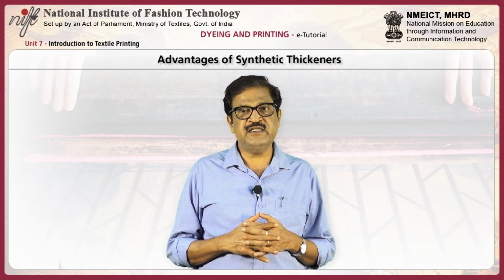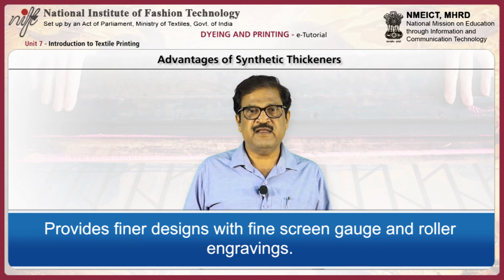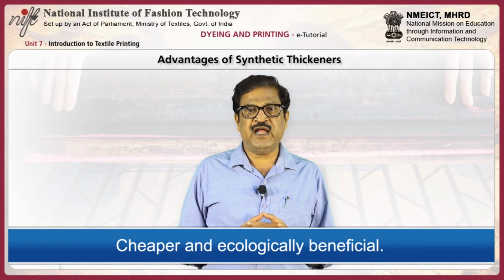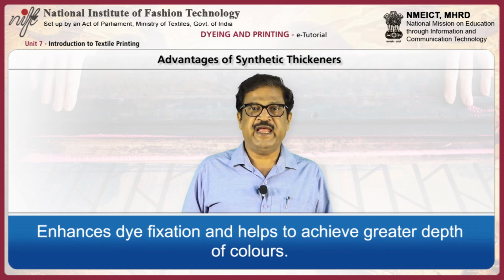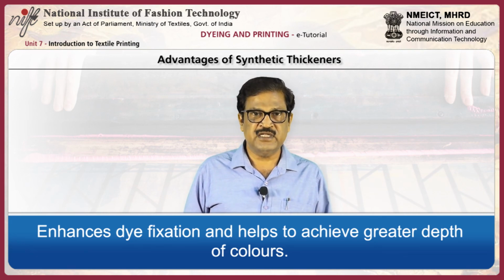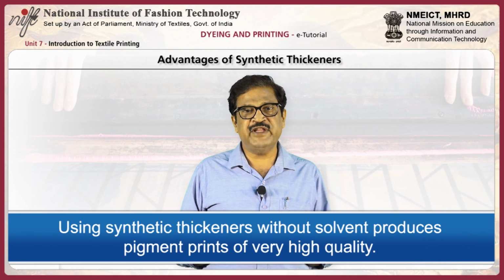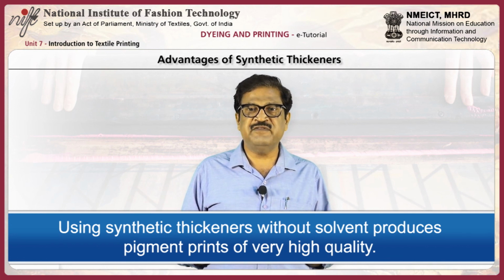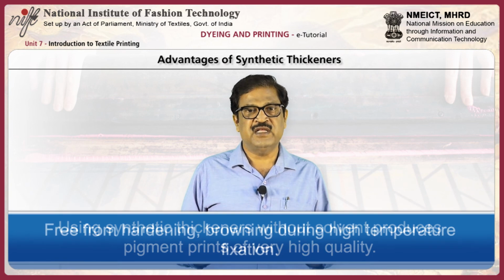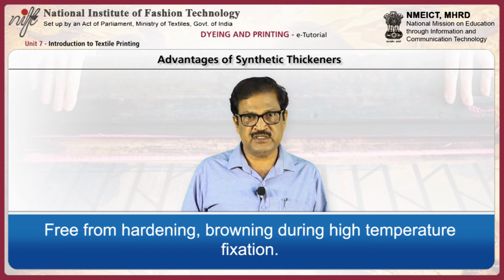Advantages of synthetic thickeners. Synthetic thickeners are derived from suitable vinyl compounds. They provide finer designs with fine screen gauge and roller engravings, are cheaper and ecologically beneficial, enhance dye fixation and help to achieve greater depth of color, and require no special storage requirements. Synthetic thickeners when used without solvent produce very high quality pigment prints. They are free from hardening and browning during high temperature fixation.